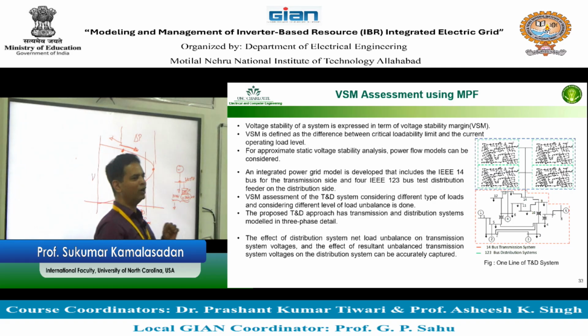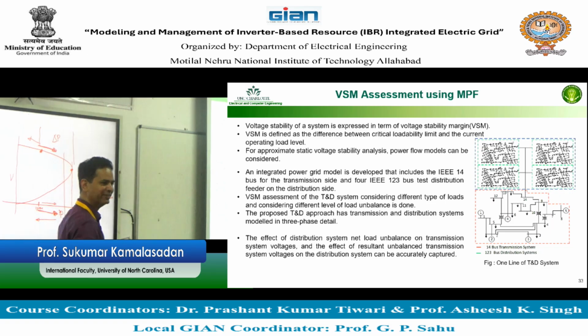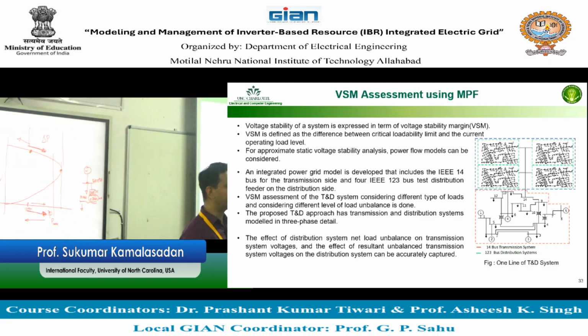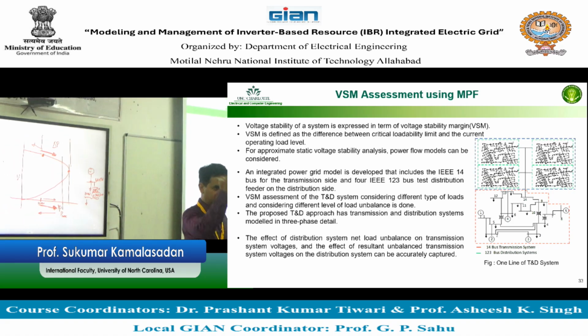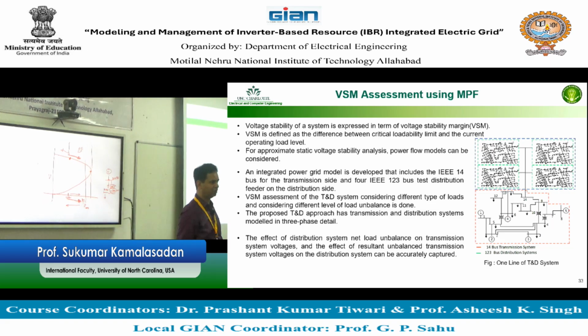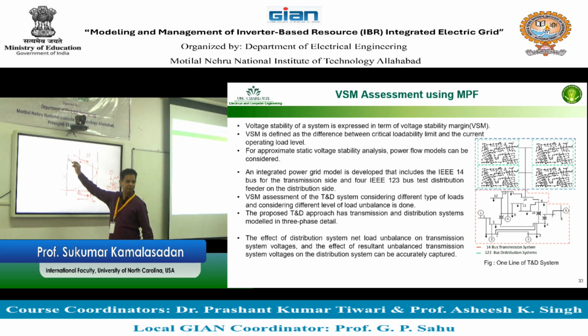So now the old PV curve, which you always see only on one side, you have to now start looking at the PV curve both ways, going this way. Is that logically making sense? Yeah, it makes sense. When you connect the photovoltaic at one point, the voltage is rising at that point because you're pushing the power like a generator. You have to balance that voltage. That's your job. Now you can also get an overvoltage at this point, right?